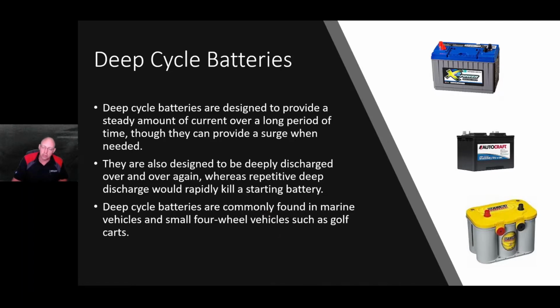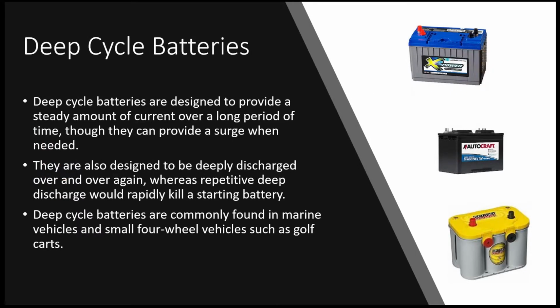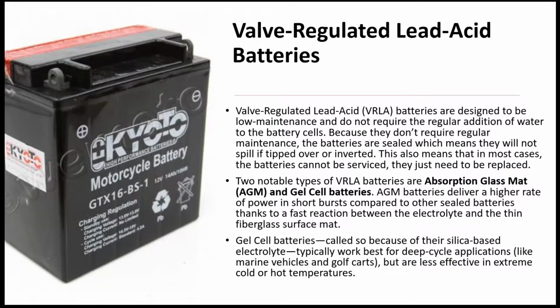Okay, moving on to the next slide. Then we have the valve regulated lead acid batteries, or VRLA batteries. They're designed to be low maintenance, and they don't require the regular addition of water to the battery cells. The batteries are sealed, which means they will not spill if tipped over and inverted.